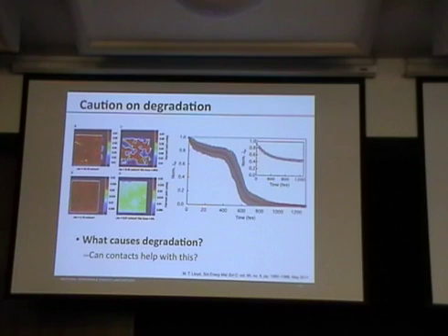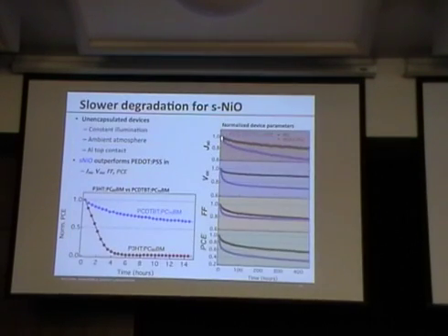Having said that, Moritz also warned us about extrapolating. And this is some device data that we took with Mike McGehee. This is basically just a bare oxide layer, and this is PEDOT:PSS. And you see that we get this kind of degradation until we reach some critical point, and then it tanks. This is the reference here, work that was led by Matt Lloyd about a year ago. And if I go back here, a lot of these, yeah, they're not bad, but we may not be far from catastrophe, right? And we just want to be aware of that.